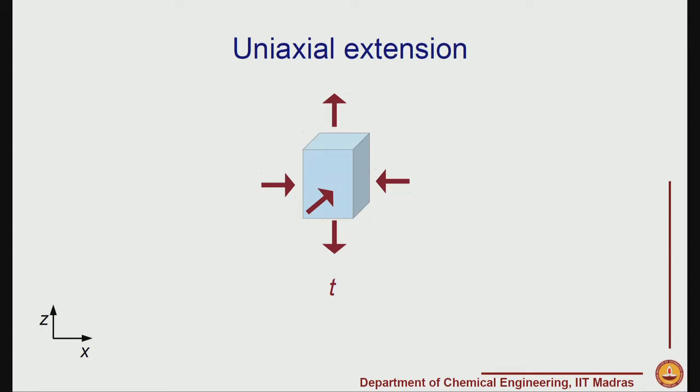You see, one of the things that we would try to do, for example, is do an experiment at a constant shear rate or a constant extension rate, right. If you remember your solid mechanics, always the tests are done at some constant strain rate. It will say 1 mm per minute or some such rates are there, and that rate is used to tell basically at what rate to apply the load, right. So, let us say we are interested in doing constant strain rate experiments.